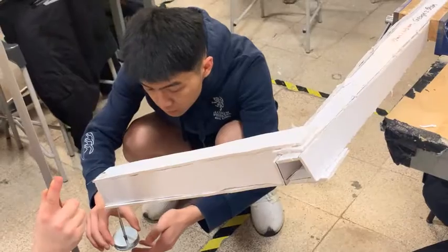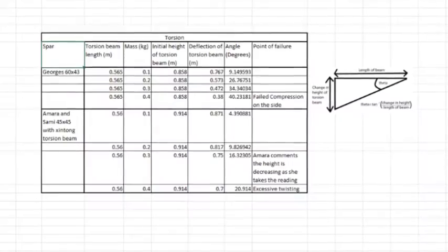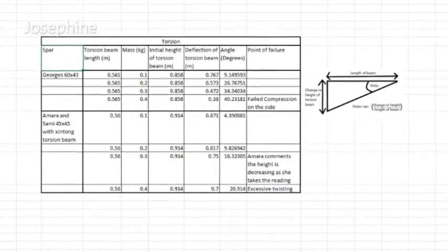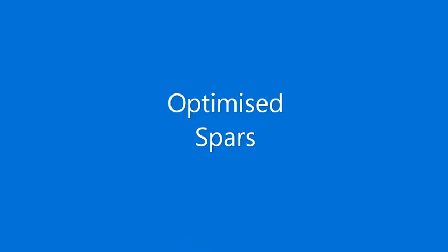To minimize twist angle, we designed beams with mass concentrated to neutral axes because the angle of torsion is equal to the semi-span divided by the shear modulus times the polar moment of area. Because bending moment is equal to the load times the span minus the distance from the root, as distance increases, the bending moment decreases. Therefore, to minimize spar mass, taper the spar.